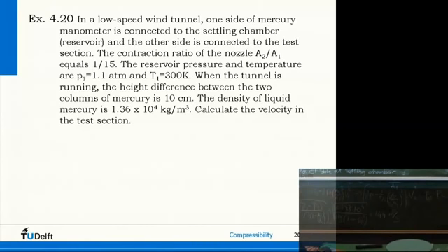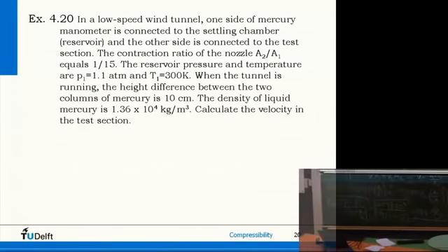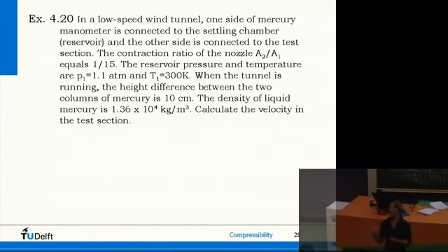So this is a bit of a nasty example. I won't do this in the exam because you cannot actually solve it. We didn't give you the information for the compressible flow, but it's very good that you're aware, because I will show you later what difference it makes quite often. So the speed is above 100 meters per second. I should have used compressible. Later we'll look into the differences actually. It is not a very discrete difference. From the second form of the isentropic flow relations I'm going to derive later, you will see that it's not a strong difference, so it might change 7 or 8%. But I'll do that after.